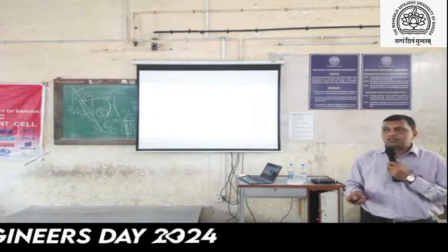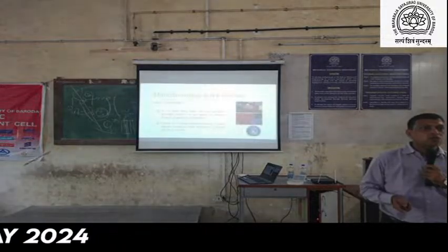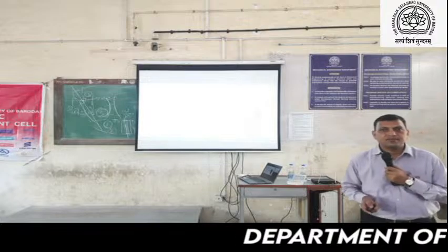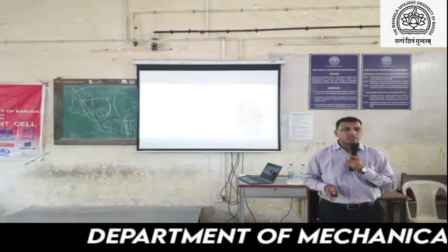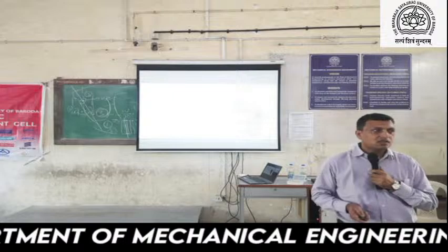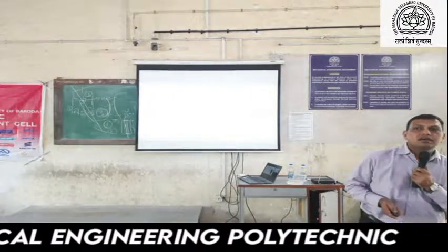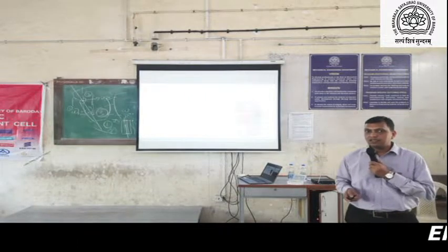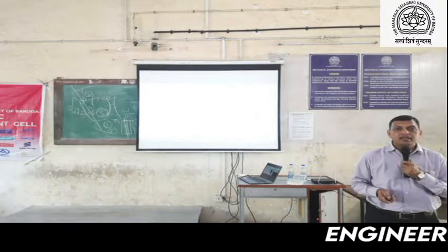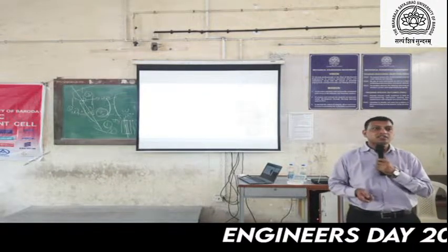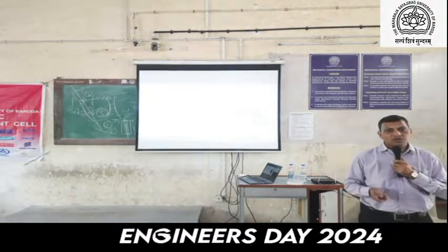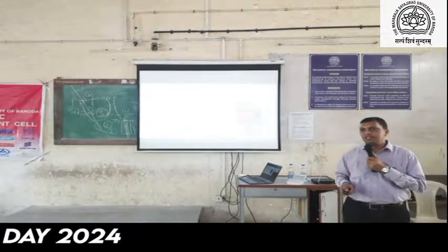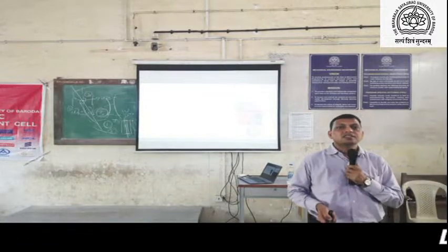After hobbing, we need to go for the heat treatment of this pinion. So why is the treatment required? Basically, there are through hardened material and case hardened material. Two materials are there. If the loading is not high and the speed is not very high, then in that case we can use soft material for our transmission. But if we require higher load capacity, then we have to go for the case hardening of the material.